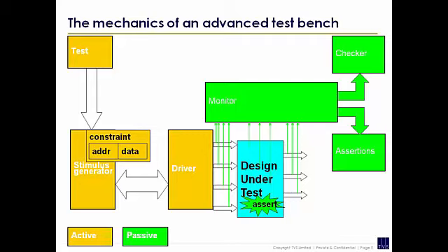Well, sometimes you deliberately put an error in this packet. So when this packet arrives here, it gets rejected, because you need to do error checking as well. Sometimes you deliberately put an error in here, and the driver will pass that error on. For example, if you're passing data that has some sort of ECC check on it, and you put a bug in the ECC calculation, then this should reject that data. But you want to test that, so sometimes you deliberately inject bugs in this. But when you develop this environment, that's when you check it and try to check it all.